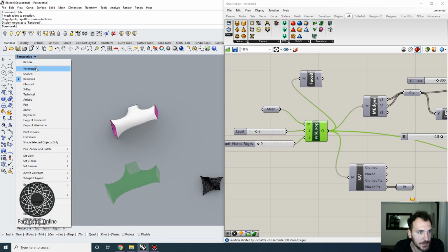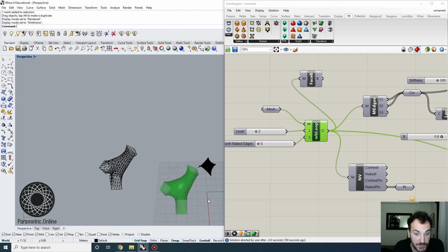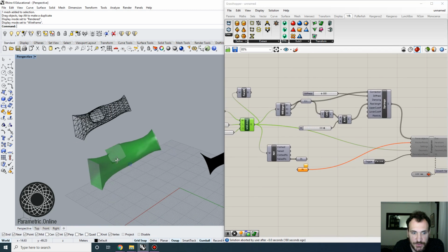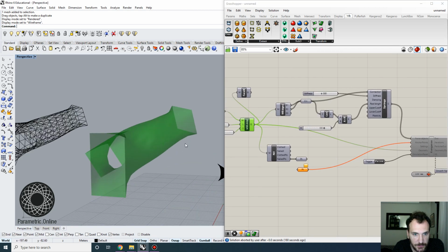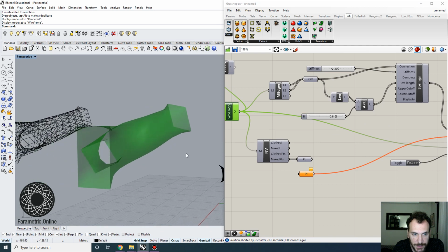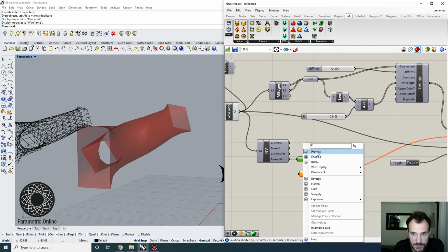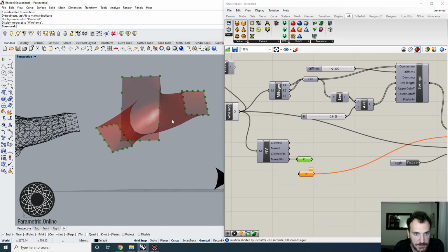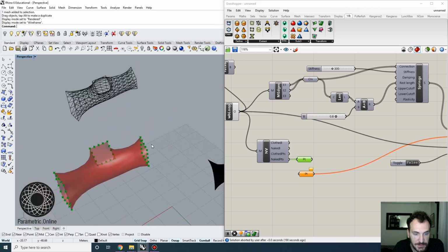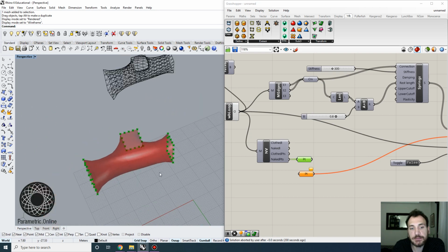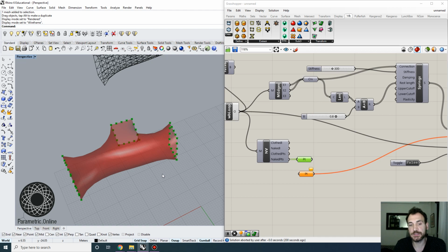So that's why we need a tool like Kangaroo to actually smooth this out for us. So how is it going to smooth it out? Well, this already has some naked points. So after the subdivision, if you turn on these naked points, you can see that it grabs onto the deleted faces. So that's the reason why I'm deleting those faces. If I don't delete them, this tool would not recognize them as naked points.